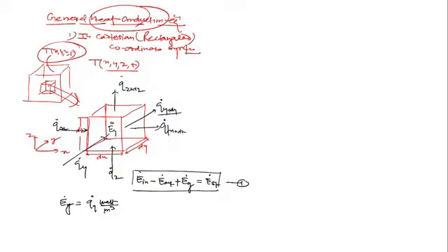So per unit volume of this material, let's say I am talking about material made of a nuclear source, then obviously it will generate heat as well. So q dot g is watt per meter cube. In unit volume, how much heat will generate, q dot g, then the total volume is how much? If you multiply with the volume, this is dx into dy into dz, which is meter cube.